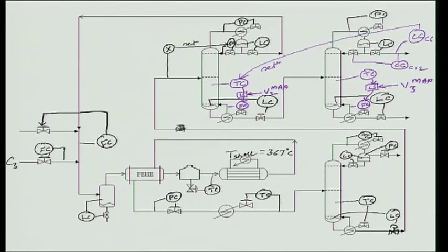Now, let us say I am increasing throughput. Strictly speaking, I want to operate the process even in mode 1 at as high a boil up as possible in the recycle column. So, I want V2 max, I want the temperature to be controlled, because if the temperature goes uncontrolled, what that will mean is that too much benzene can leak out and contaminate my product.